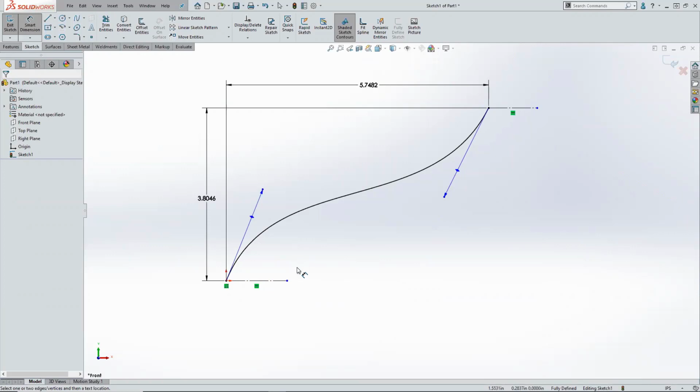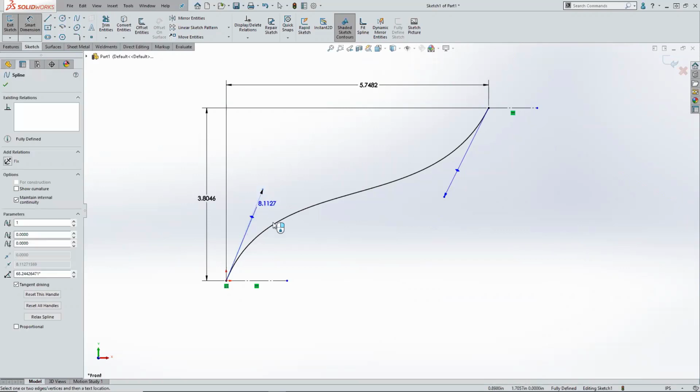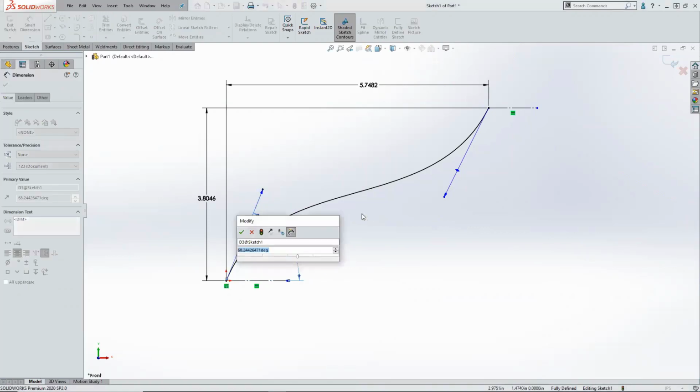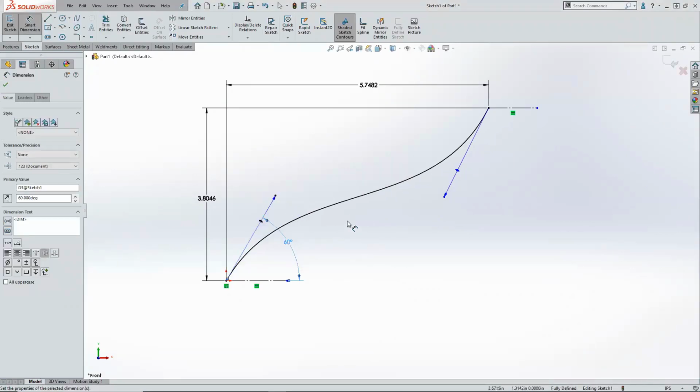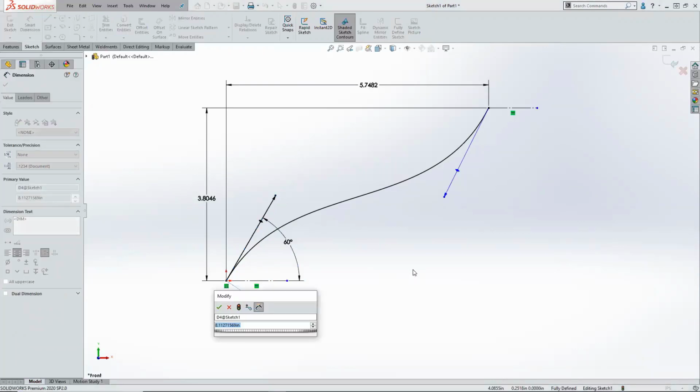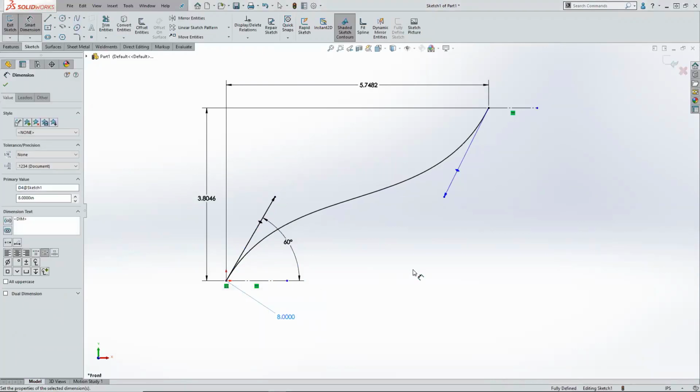And when you're putting in dimensions relative to these control features, you're going to notice that I'm going to grab that and this line, and I have to grab this control handle by the point. And I can set that angle. And even if you adjust it, you're going to see that it is going to adjust and to be far more precise than what it was before. For that radius, I'm just going to click that point at the very end. Okay, and I can adjust it to whatever I want.